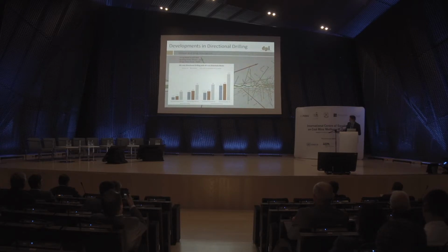What we're doing here is we're looking at various configurations of drill steel size versus casing size at a certain weight on bit that we want to achieve, and using that to design a wellbore plan that's going to allow us to achieve the depth that we want without any helical buckling or other issues that are going to cause us to limit and not achieve our objectives.